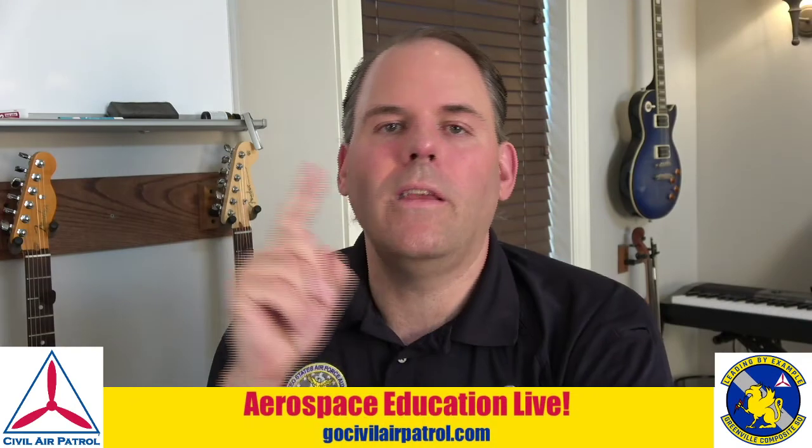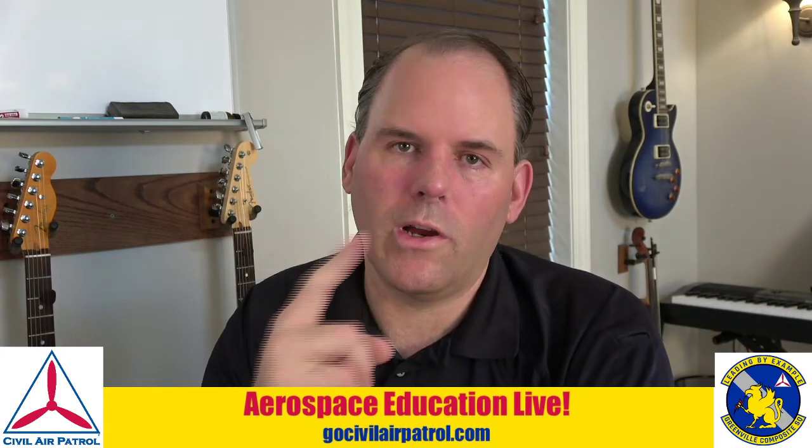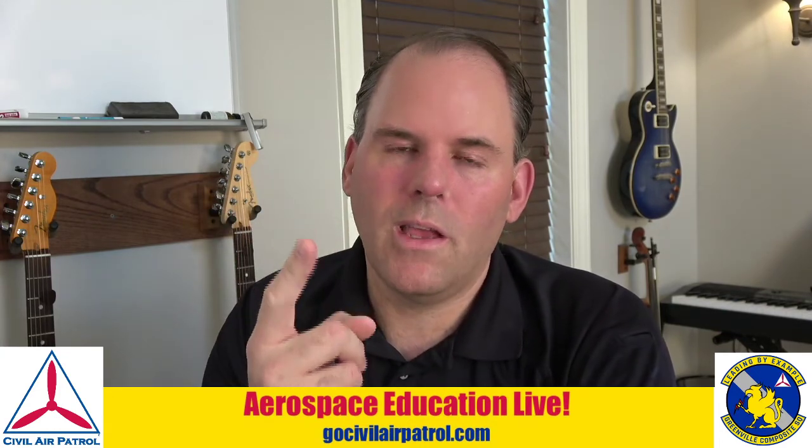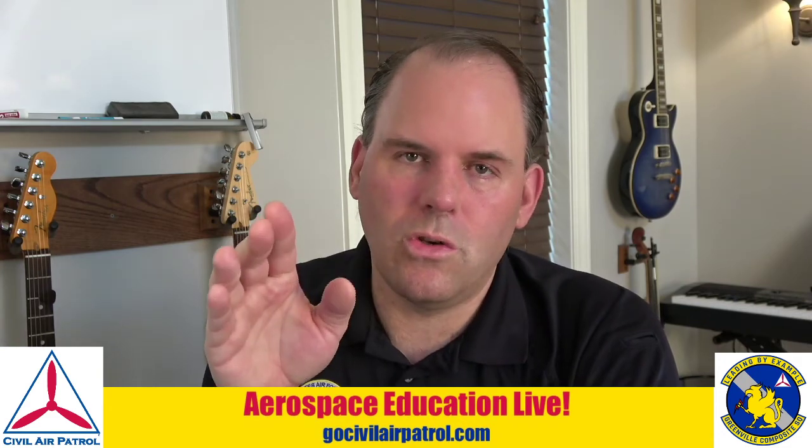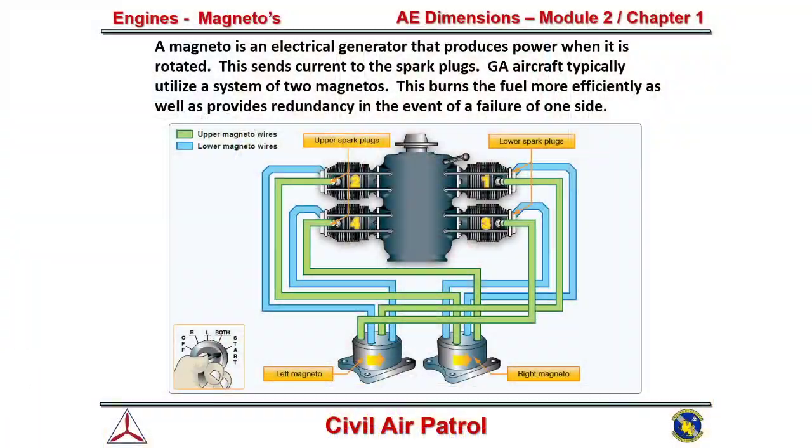All a magneto is, is a spinning motor, and when it spins, it causes an electrical discharge. The electrical discharge goes to the spark plug, and that's what gives you your spark during the ignition, or combustion, phase. All right, so that's important. The other thing it does is it gives us safety. If one of these magnetos failed, let's say this left magneto here failed on you, you would still